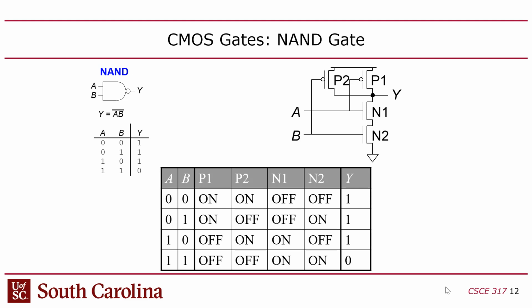And so because there are no 0 inputs in an AND gate to pull it up, it's impossible to build an AND gate with a single CMOS gate. You might say, well, someone's built one, right? Well, yeah, the way you build it is you take a NAND gate and then add an inverter on the output, right? You can't build an AND gate with a single CMOS gate. You have to build two gates together to realize an AND gate.